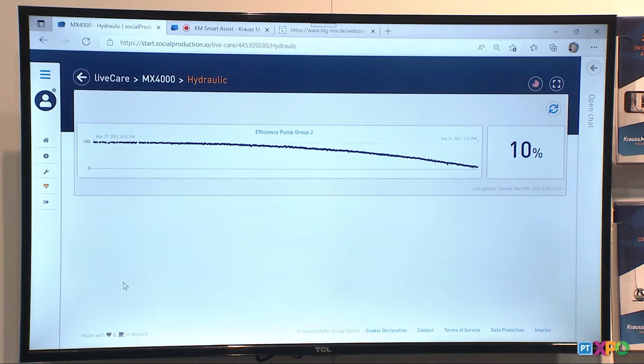I can graph that out and see how my pump is performing during a certain period of time. I can actually see some peaks or some not very efficient running, and then right at the end get my efficiency percentage. And that will be a very important indicator that will help us program our stops, our maintenance, or get better programming on whatever changes your machines might require.